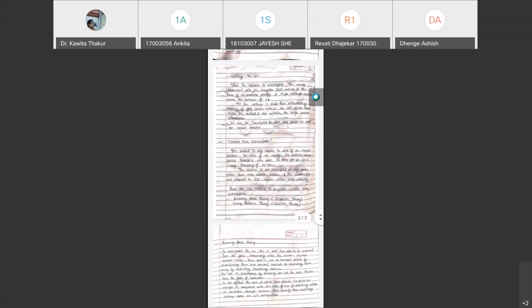Next is current zero interruption, and this method is applicable only in case of AC circuit breakers. In case of AC supply, the current wave passes through zero 100 times per second if the supply frequency is 50 Hz, and the current is not interrupted at any point other than zero current. The current will also not be allowed to rise again after zero crossing.